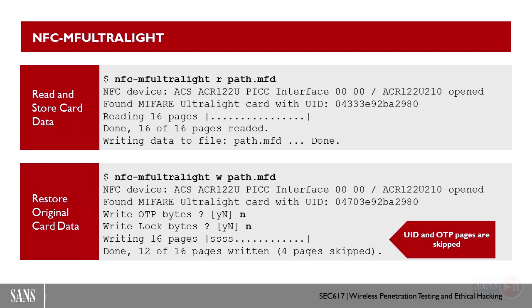Some things to think about for you guys doing lab and CTF. The tools that you have on the Raspberry Pi are specifically neutered to never write to the one-time programmable bits. Because what will happen is you guys will be using these style of tools to bypass a system for some parking as part of lab. And if you accidentally write the one-time programming bits, you can never update the MIFARE Ultralight card ever again.